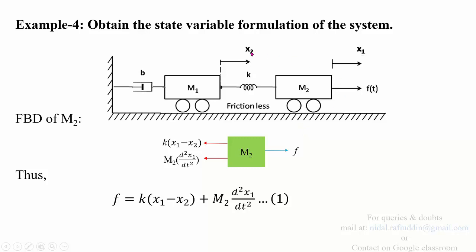But for the time being, we say that it will be having four state variables because for masses we assume two state variables, displacement and velocity. And since you have two masses, that is why we'll be having four state variables, displacement and velocity corresponding to each mass. This can also be clear from the differential equation that we see here.